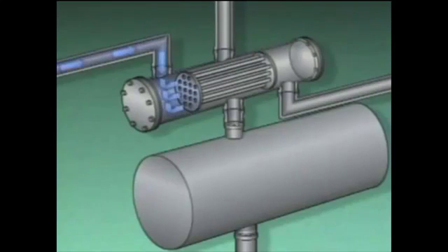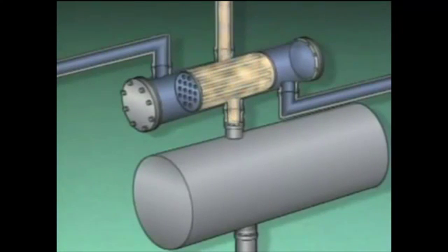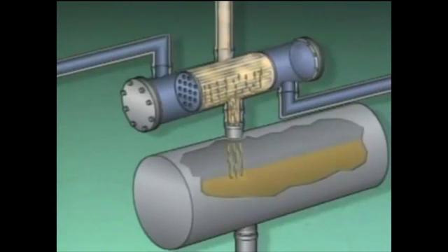During normal operation, cooling water enters the cooling water inlet, fills the water box, and flows through the tubes. The cooling water then passes through the outlet water box and leaves through the cooling water outlet. At the same time, the product vapors enter the condenser through this vapor inlet and flow around the tubes. When the vapors come into contact with the surfaces of the tubes, heat is transferred from the vapors to the cooling water in the tubes. As a result, the cooling water is heated and the vapors are cooled. This causes the vapors to condense on the tube surfaces. The distillate drips off the tubes and flows through the distillate outlet to the receiver where it collects.